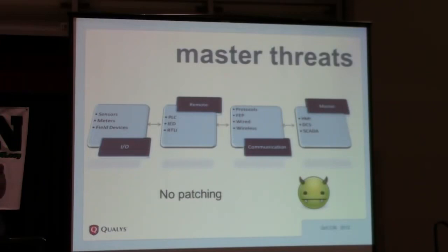This is a pretty interesting subject as far as SCADA systems are concerned, which is basically no patching. A lot of SCADA systems that we saw, none of them were patched, unlike your IT systems which are on Windows and whatnot. None of them were patched. Any guess on why that's happening? Are all SCADA engineers lazy or something, or what's the reasoning behind it? They don't want to break the system. So, no, SCADA engineers are not lazy.